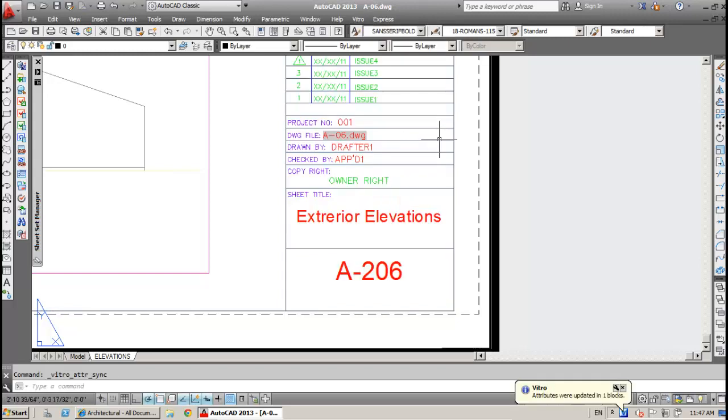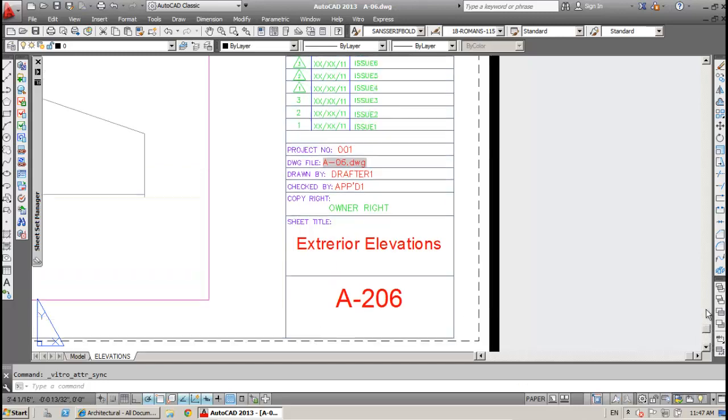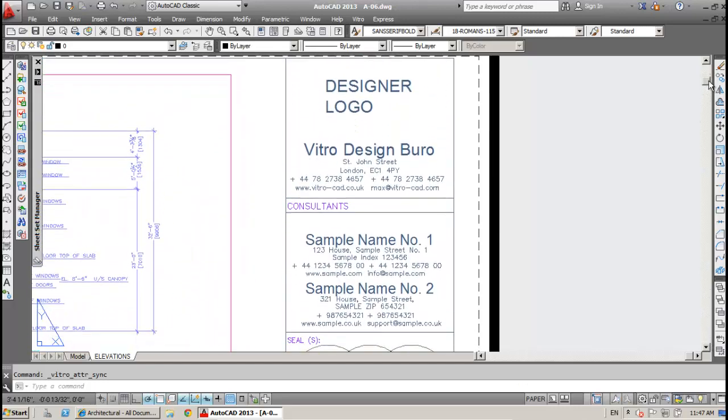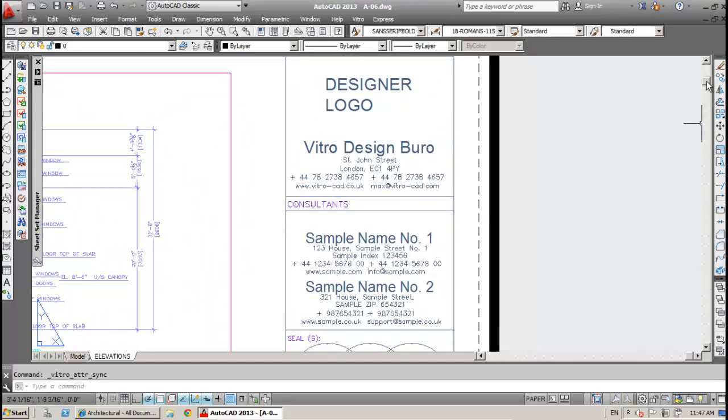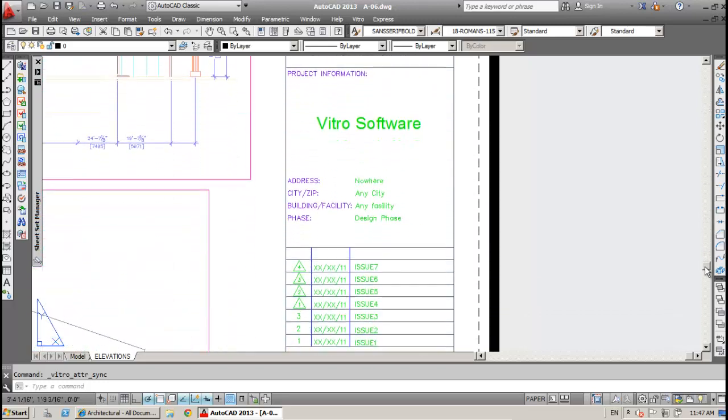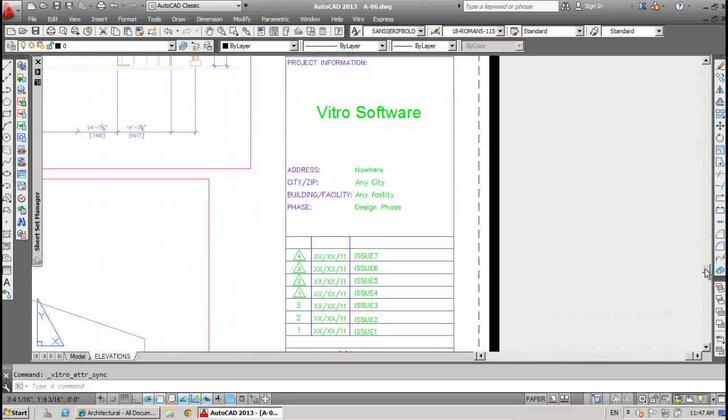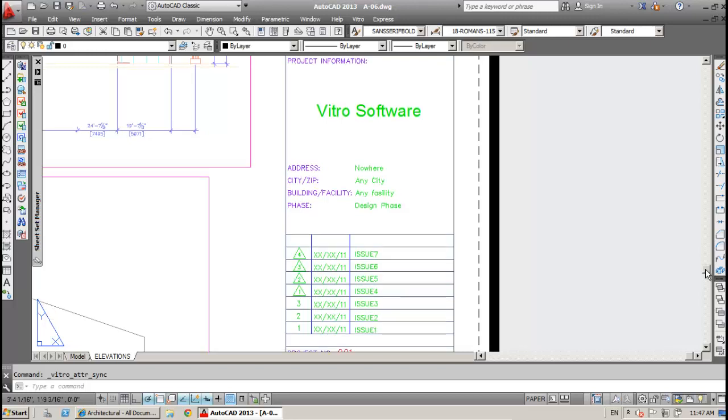Right, done. In my example, the designer ID block is synchronized from an XML file, which contains the designer name, address, and other data. All this data is global for the repository. Then I have the project ID block. This data is stored in Project Library CAD and contains the project name and building address, and is constant for all the files and drawings inside this project.